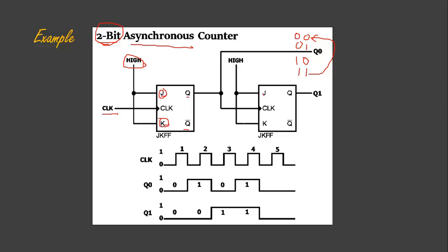One thing is there, these flip-flops are a kind of negative edge triggered flip-flop. So there should be a bubble and an arrow. This indicates the clock, this indicates the negative sign. Similarly, this one is also a negative edge triggered flip-flop. This is a JK flip-flop. This is flip-flop 0. This is flip-flop 1. This will be Q0, I can say, and this I can say Q1. Doesn't matter. It is mentioned here.